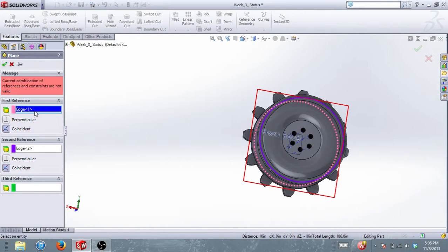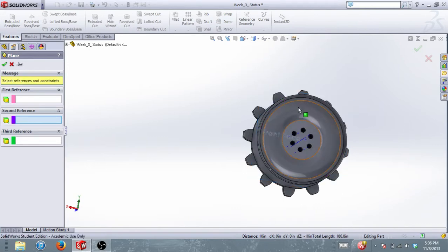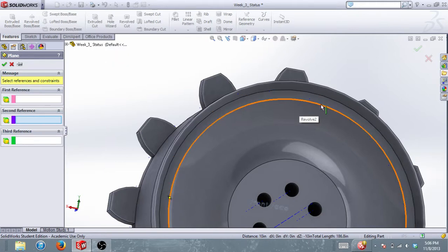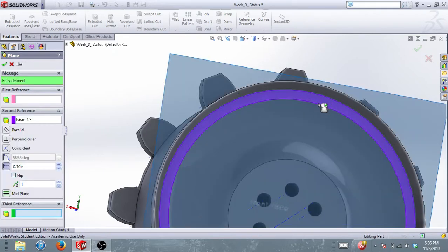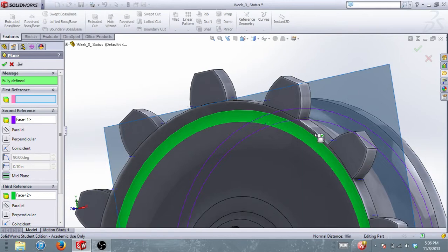Sorry about that, let's delete both of those. So I'm right clicking on these and deleting. Instead of the line, you want to select the face. So that selects the line, that selects the face. See the difference? How it goes from a bold line to a light one. So now my face is selected, and select the same face on the other side.